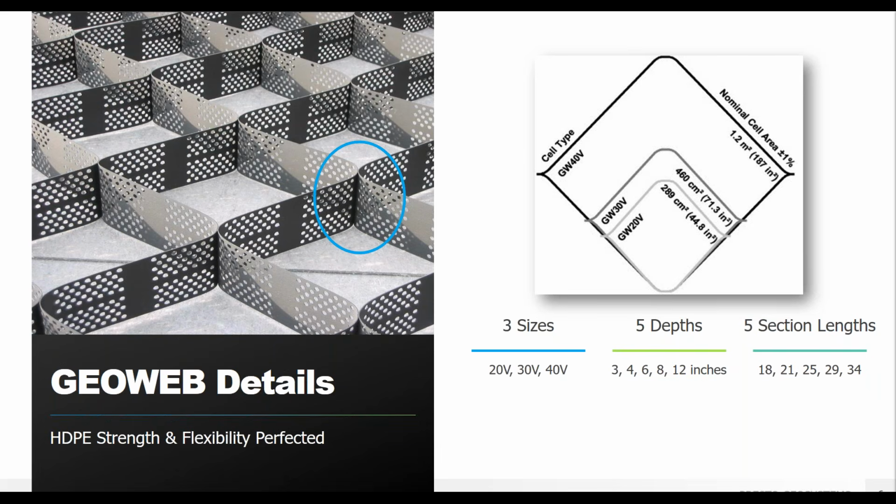So to avoid weld failures and the damaging effects of differential settlement, uniformity in the performance across all of the different elements of a geocell system is going to be much more important than stiffness alone. And so I kind of threw a lot at you right there. And it's not necessary that you remember every single term I just said.